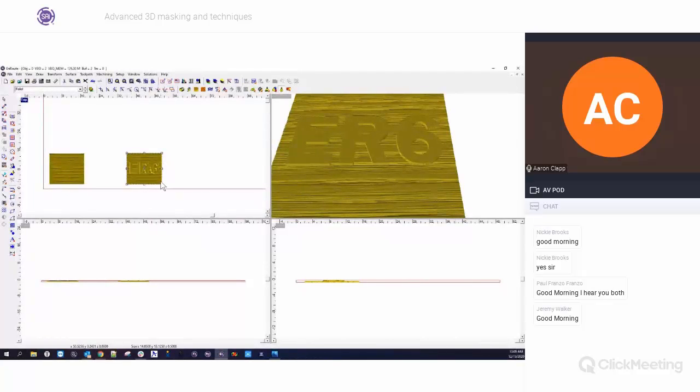Now, the disadvantage is that as your machine goes back and forth in between these letters to cut all this out, when it hits a letter, it's going to have to lift up, scroll across, go down, and then lift up and go over and down. It's going to do this process repeatedly. Even with an island fill, you're going to get the same result. It's going to have to lift up and over these letters. So you're going to have a very inefficient toolpath.